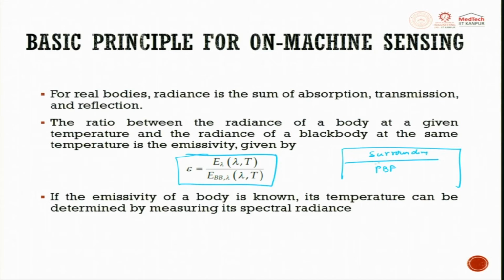The temperature gradient can be figured out, and if the gradient is small, then you are able to produce a sound quality output. If the gradient is very large, it introduces thermal stresses. Thermal stresses mean residual stresses are there. It might lead to delamination or cracking.